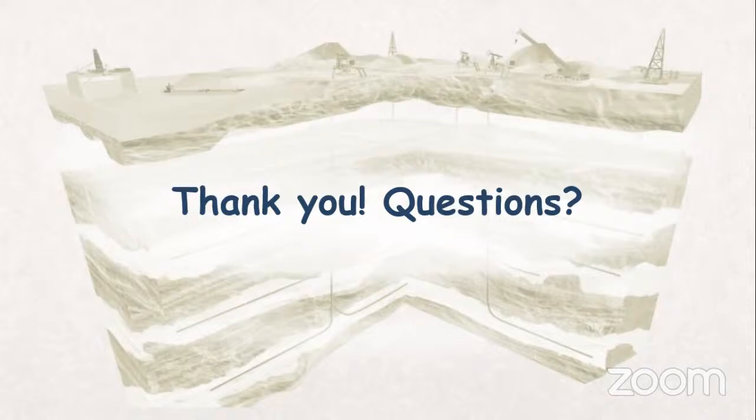Okay, I have another question. How did you conclude the gas cap? Yeah, I was trying to answer this question during the presentation. It can be due to the limited drainage area of each branch of the well, right? In case of a gas cap, an increase in delta P. Right, so whenever we have a limited drainage area of each multilateral, I'm just trying to imagine the situation. That would mean that our boreholes, our side tracks, would not actually interfere. We will have a limited zone for each lateral, and then the pressure derivative would go down.